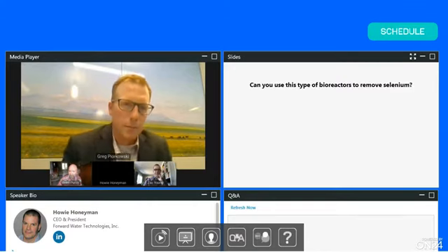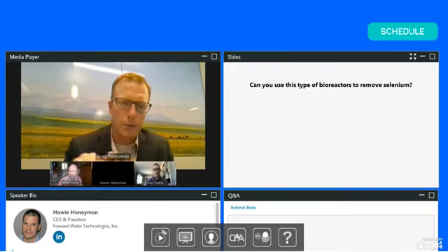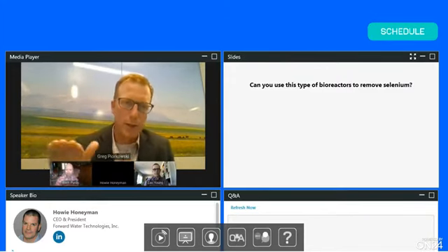So selenium, from my understanding, is kind of lower down on the food chain with respect to biogeochemical processing, whereas nitrate is basically just, so what happens is the bacteria degrade organic material and then they're looking for an electron receptor. So oxygen is the primary one. Just under oxygen is nitrate.